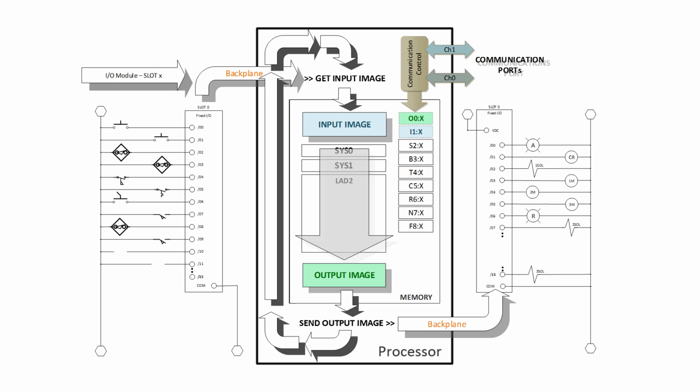If you have more than one, in this case more than one, 2, I show slot 0 for both. You can ignore that. It really doesn't matter what slots they're in. And a lot of what you call a PLC, it's really a controller. The difference between a processor and a controller is all PLCs have a processor and they have I/O interface. And you're looking at 2 I/O interfaces here, one for input, one for output. So this whole thing together is a controller. A controller has a processor.